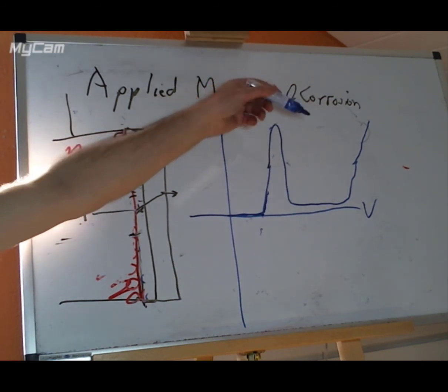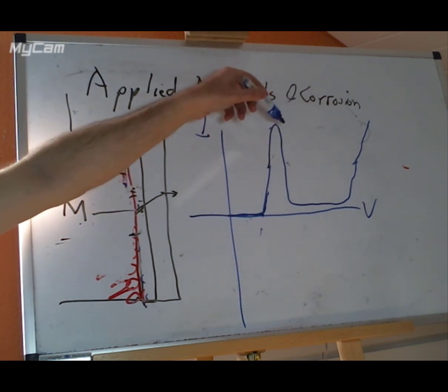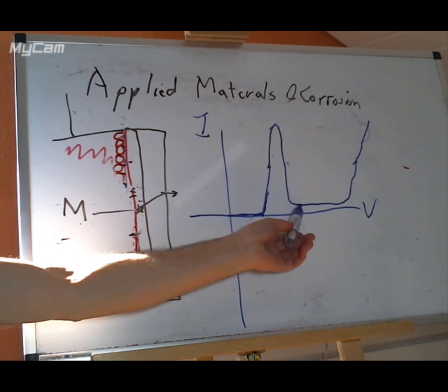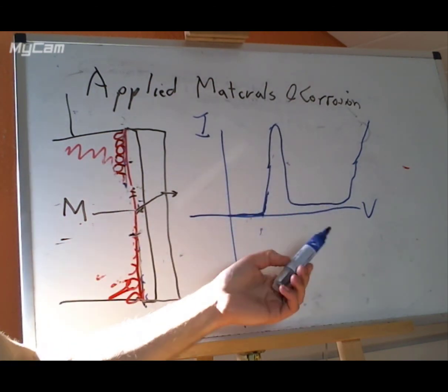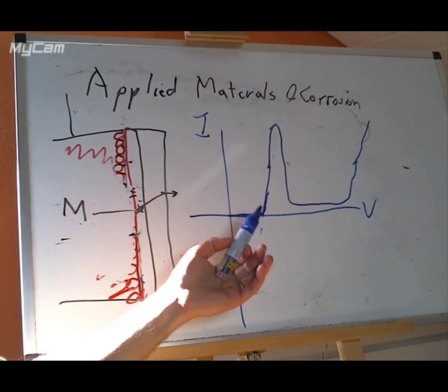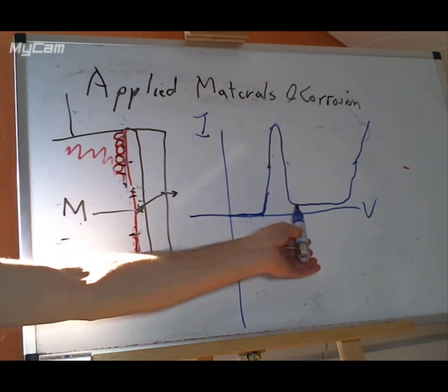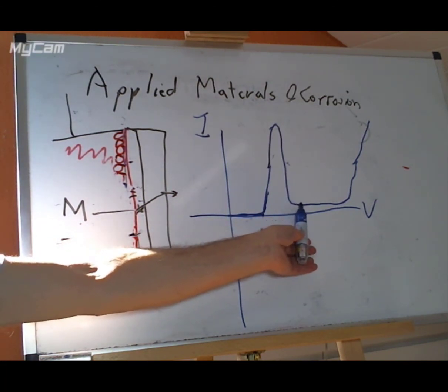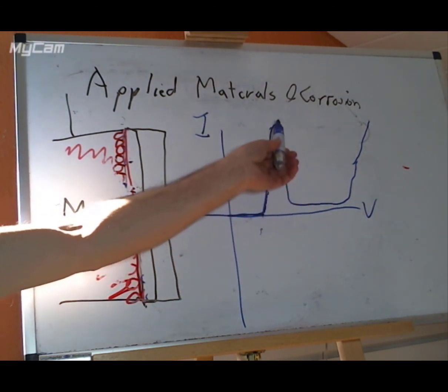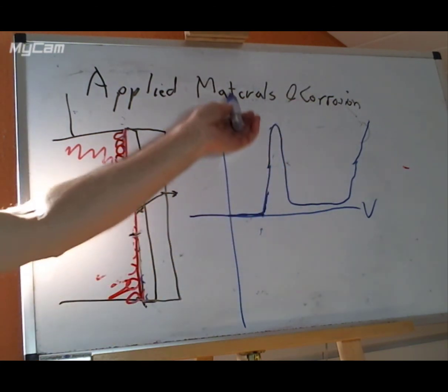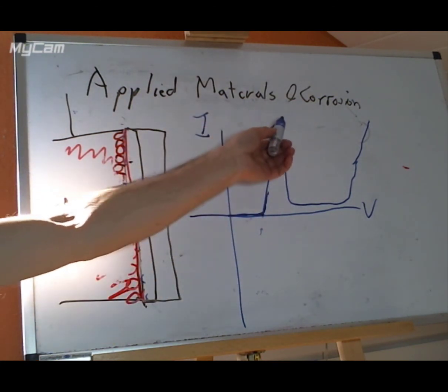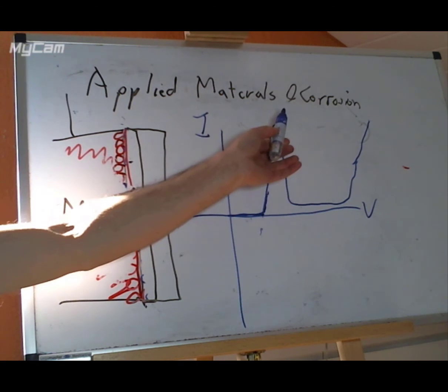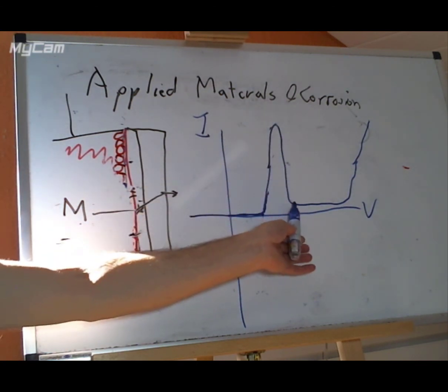And then when we reach that point where we start to make oxides, the current comes right down. It doesn't go to 0 because there is then a passivation current where we're making the oxide at the speed that it redissolves. So we can keep that constant for a relatively long time, for a relatively large range of voltage in this case.